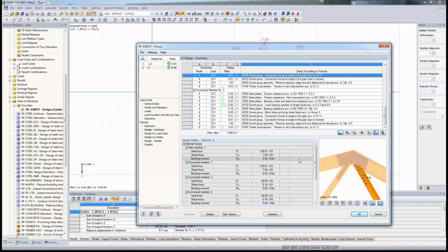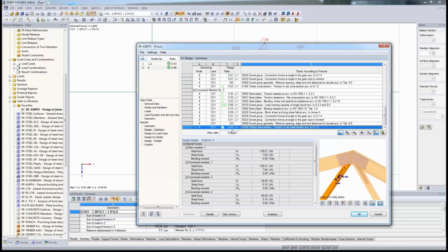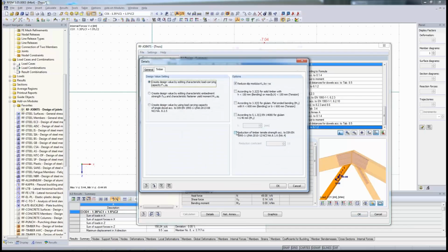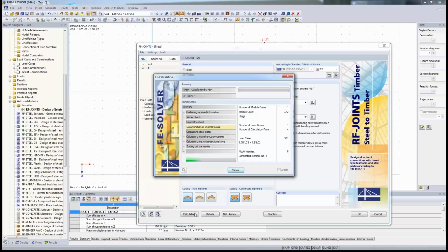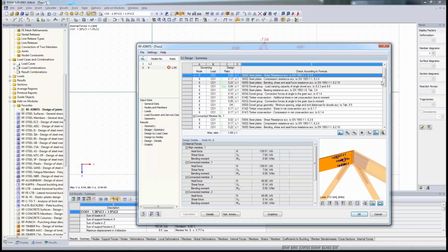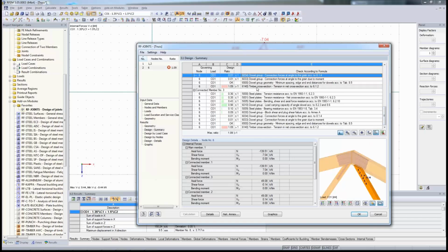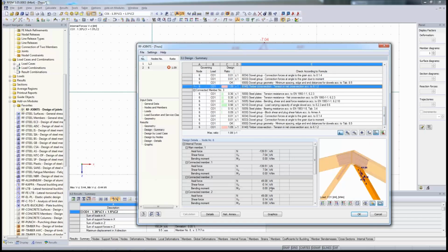Maybe if we look here, yeah, you see that's maybe something interesting. We have now a loading of 43%, but if you check on the reduction of the tensile strength, we already know now it should probably be near to overloading or overloaded, and you see it's overloaded now 9%. So that's what I said when I did the modeling.